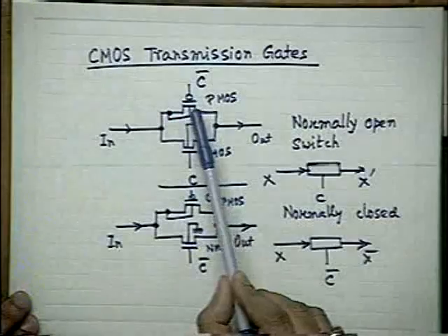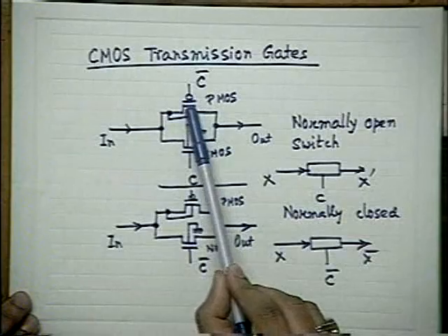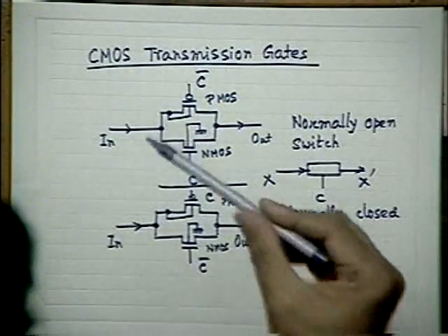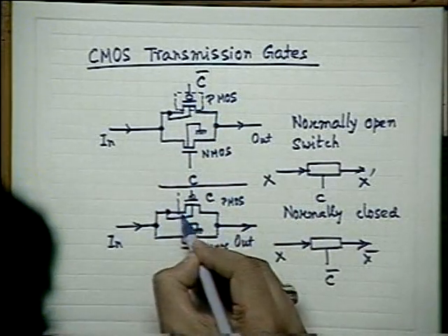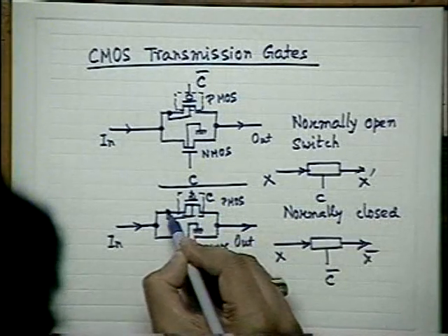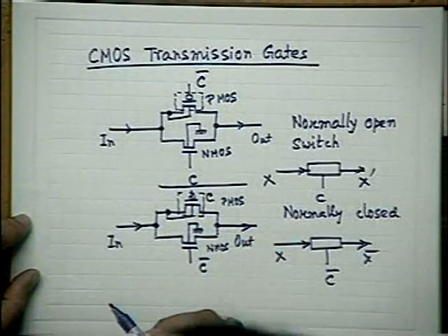You just try to remember, sorry, time is over, the CMOS inverter. The diffusion at the bottom is the source of the nMOS, whereas the diffusion at the topmost point is the source of the PMOS. That way it is just the opposite kind of thing. Exactly that is shown here. The substrate here, this is not substrate, this is the N well. Please remember, whenever I draw PMOS, it is sometimes preferable to draw a block. This dashed rectangle indicates the N well. This N well is shorted with the source. So this is the source side. This has to be kept in mind.